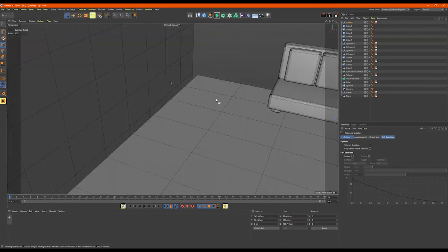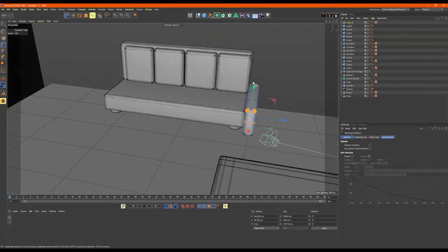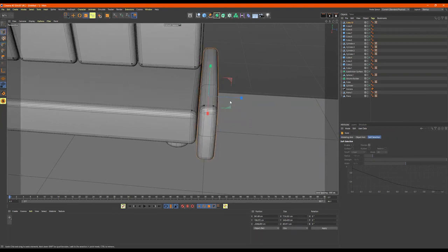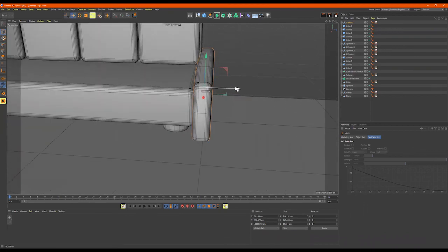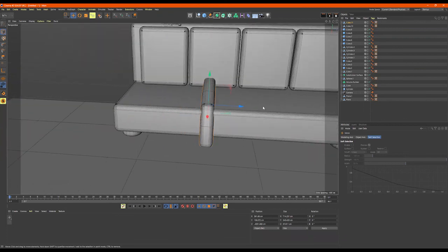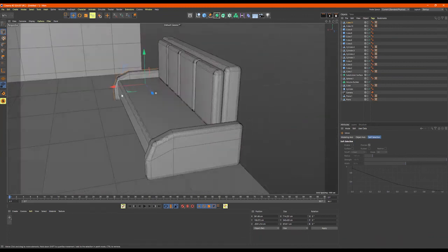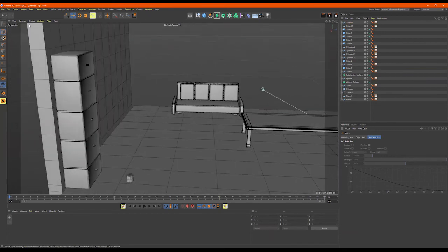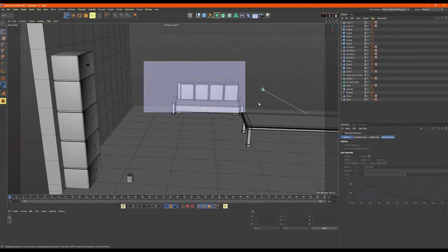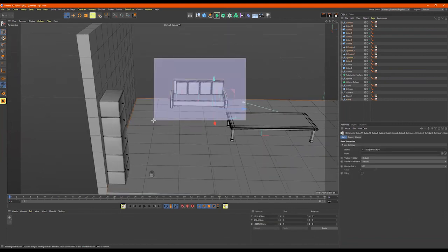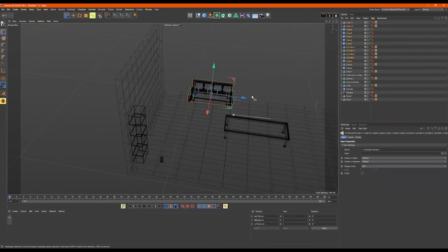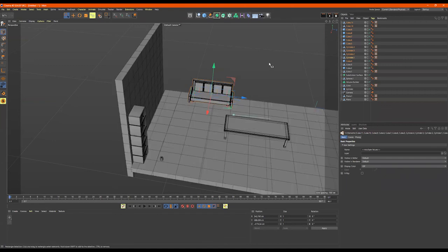All right. I'll just put it in this mode, T, just scale it a little bit. Control click. All right, so I got all that done. Then I'll do my rectangle selection. I'll try to select all of these. Control deselect what I don't want. NG just to make sure I'm getting the sofa. NB. And then I'll do an Alt G.